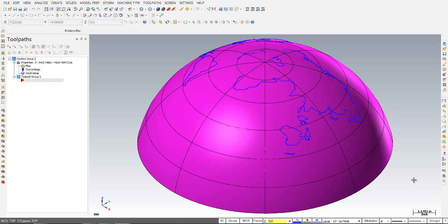In this video, we will create a curved 5-axis toolpath with tool axis control oriented to a point. The curved 5-axis toolpath can create a 3-axis, 4-axis, or 5-axis toolpath along a 3D curve or along one or all edges of a surface. The tool axis can be oriented parallel to existing lines, normal to a surface, normal to a plane, oriented from a point, or to a point.